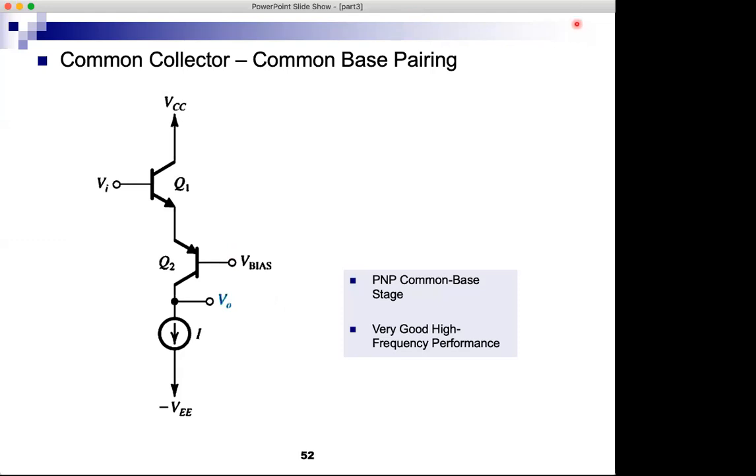Okay, so the choice of NPN versus PNP, how does that affect the amplifier? Actually, in small signal analysis, NPN and PNP, from the point of view of analyzing the amplifier, they're the same. They have the same small signal model. They appear as if they're just a BJT, but generally, PNP and NPN are different in the polarity of the current. So in the case of NPN, the current enters into the collector. In the case of PNP, the current enters into the emitter. In the case of biasing, it makes a difference.